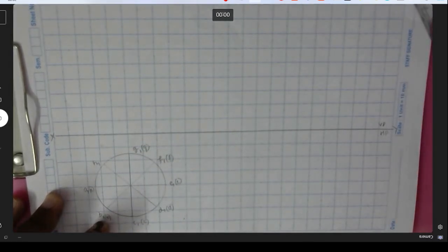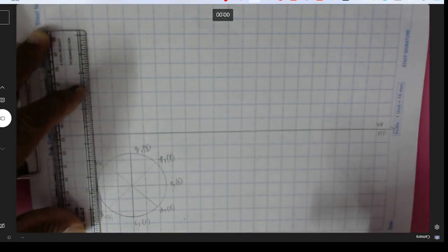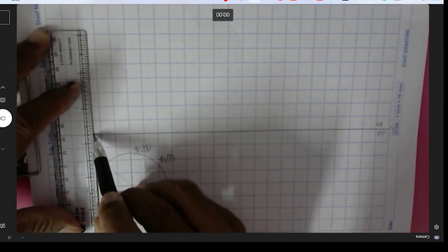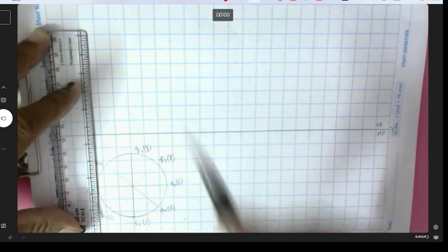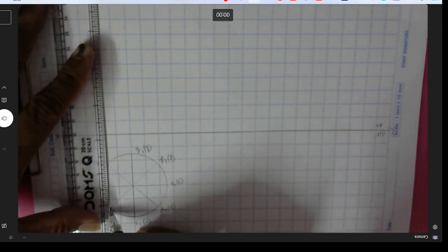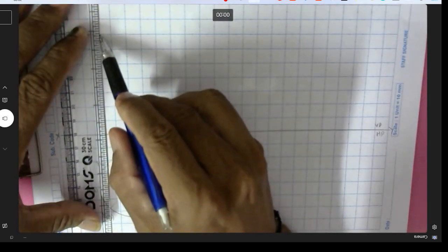Okay. Now let us construct the construction lines to obtain the front view above the XY line. Height is 70 mm. So 1 2 3 4 5 6 7. Okay, similarly produce construction lines from all the generators over the XY line.